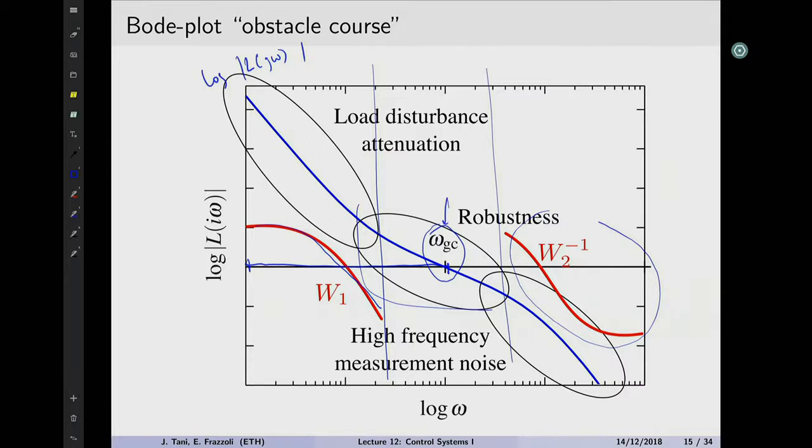imagine always frequency content as a speed of variation. So if I have a high frequency signal, what does it mean? It means a sinusoid at high frequency, something that can vary very quickly in time. So having a high closed loop bandwidth means that the system is able to keep track of reference signals that vary very quickly.